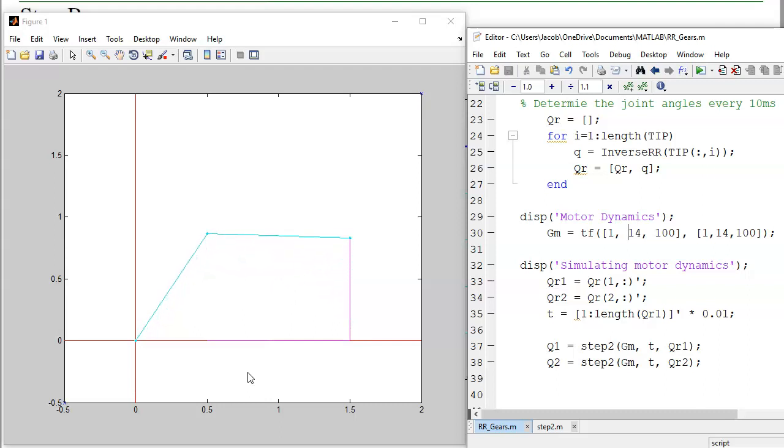And that's pretty much what the homework is for homework set number 12. Trace out a shape, like a star, triangle, pick your favorite shape. Find the motor angles, velocities, and accelerations, and then filter them like we did here. If I have proportional feedback, I just have the one term. PD, I've got two terms. PD with feed-forward acceleration gives you the three terms. And then I'll have ideally perfect tracking.